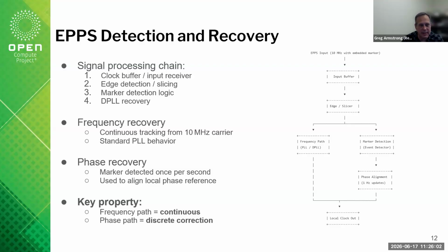So there might be something that's sampling the rising edge of the 10 meg and then sampling the edge of the feedback to say, how are we aligned? What's the phase offset? Let's close that into 0 so that I can then synthesize a synchronous clock relationship to that 10 megahertz, but it could be any multiple of that 10 megahertz. It could be integer related, fractional related, whatever it is, and that's going to be my local clock coming out.